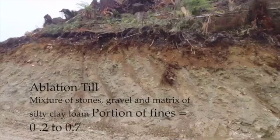The most common road surface soil material in BC is this glacial till. Virtually all of BC was once covered with glacial till, although subsequent glacial retreat has modified the terrain considerably. There is a basal till underneath. It's a highly compacted material. And on the surface, the reddish material is an ablation till, which is virtually non-compacted. It has fallen out during melting of ablating glacial ice.